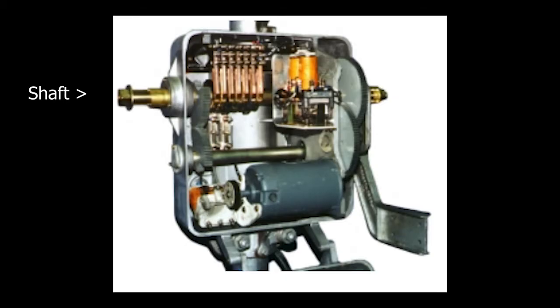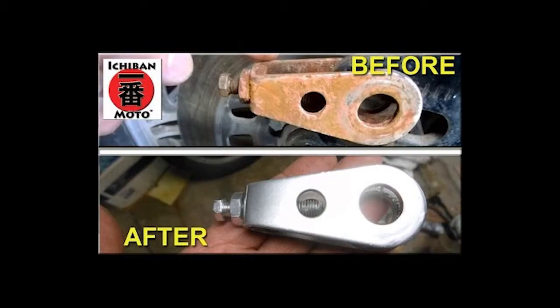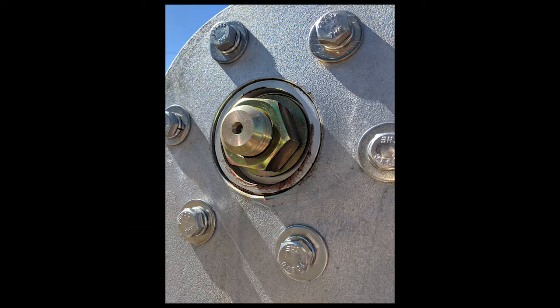Next, the shaft can be formed, with a length of 863 mm and a radius of 16.5 mm. The shaft can be coated with zinc through electroplating. As mentioned before, this would aid in protecting the shaft from corrosion, which would ultimately increase the lifespan of the metal and its functional environment. Lastly, the shaft is ready to be installed into the grade crossing signal.